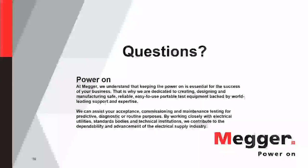Whenever I see bad results, I assume I did something wrong first, check all my connections, then I assume my equipment's wrong and verify that if I can, move a transducer around or swap it out. And then lastly, I start looking, hey, something is wrong with this circuit breaker. But as far as calibration goes for field use, once you verify that original calibration of the transducer, you're not doing it that often. I'd say 4 or 5 years would be fine.